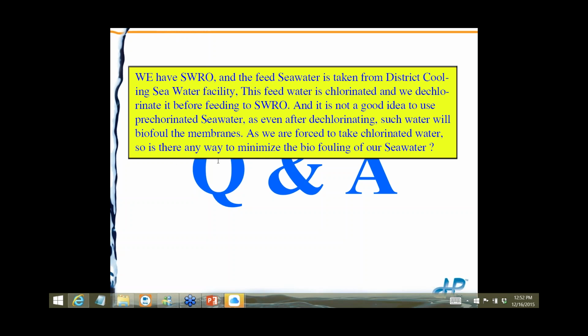What micron cleaning filters do you recommend? I'm fine with 5 micron. Scale inhibitor can grow bio and or degrade? Yes. Dilute, not full strength, but dilute.